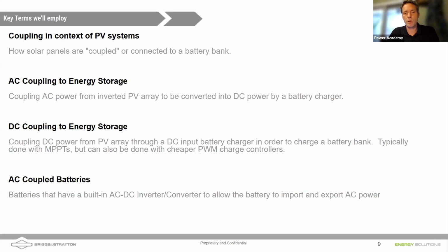And then, I do want to mention it here, there are also AC coupled batteries. What are those, Daniel? What's an AC battery? Well, essentially, all batteries are DC. It's just that the inverter and charger are built into the battery case itself so that you have multiple batteries. And you had mentioned, Nathan, that you can't decouple the inverter charger for the battery if it's all built into one, where if we separate those out, we can scale energy and power separately.